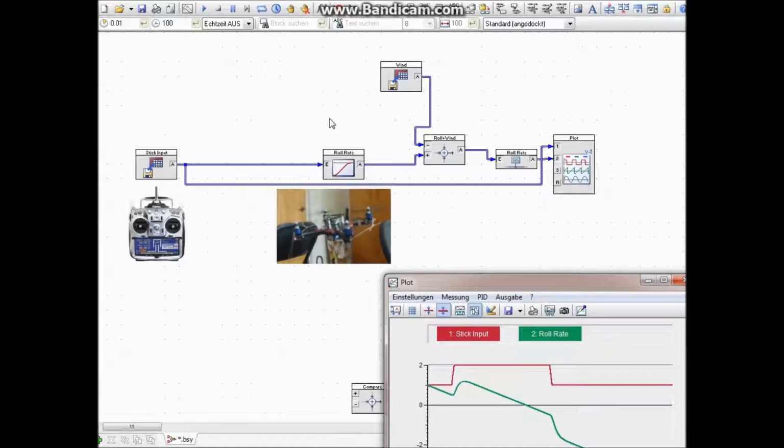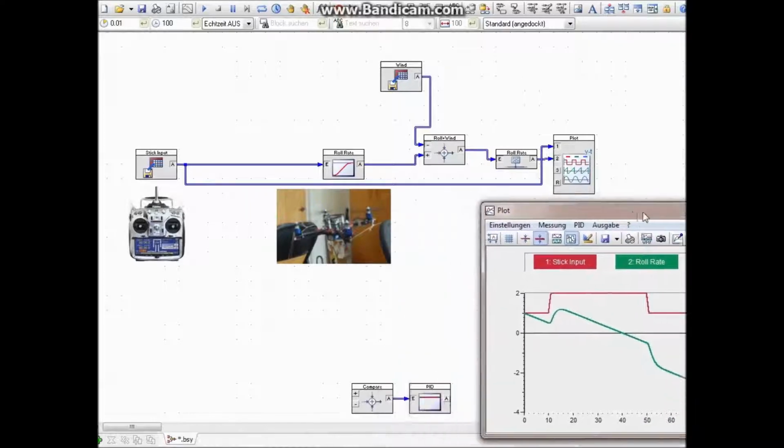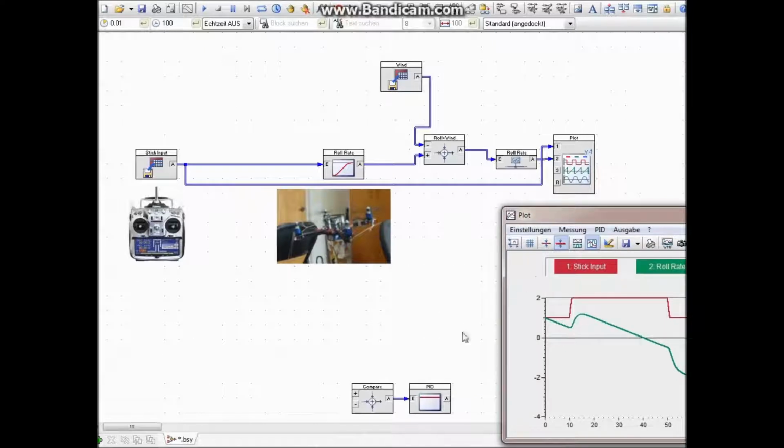And in an open loop system, you put something in, and as long as your value is good, the quadrocopter will perform. But in the moment that something different, like wind, changes the system, you get all kinds of results, and you're not able to control it anymore. So that's why we have to go to a closed loop system. Okay, now closed loop systems, this is where PID also comes into play. What do we do in order to get a closed loop system? Let's see here.